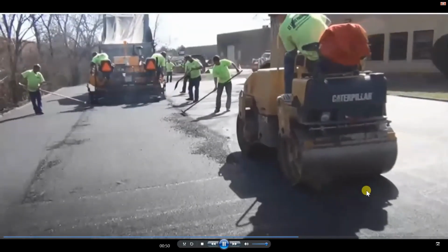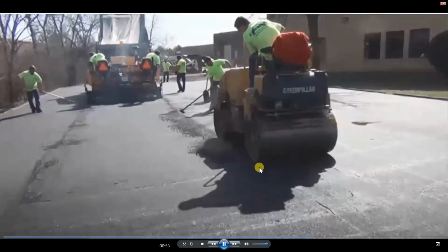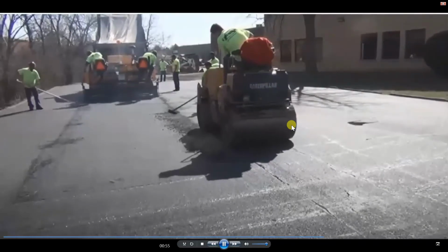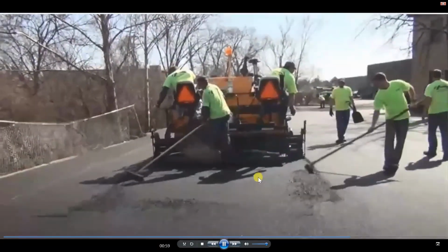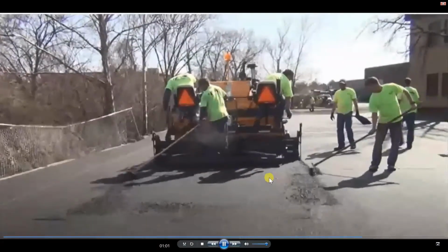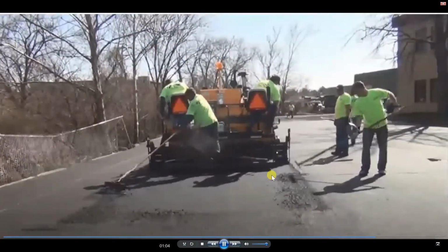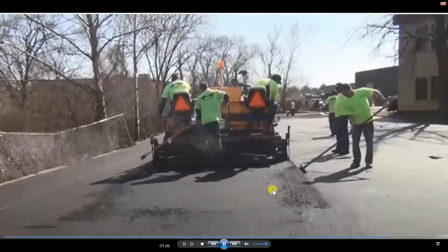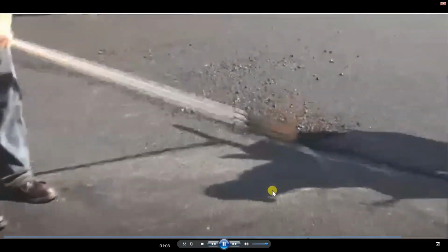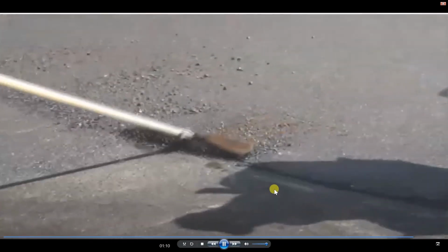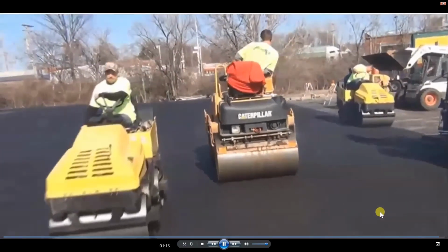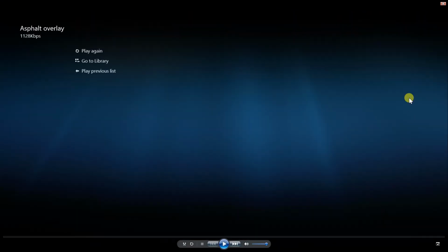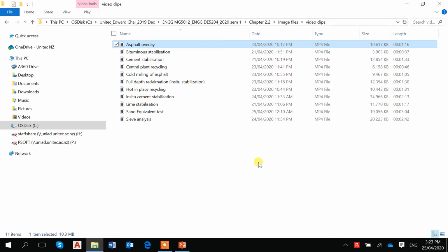Invariably, seams are where the first cracks appear in a new overlay because they are the weakest portion of the overlay. Lute stick skill, as well as crew speed, is the primary defense against premature cracking at the seams. We keep premature seam cracking to a minimum because our crews are so experienced and work so fast. As the paver moves along down each pass, a series of rollers compact the finished surface.